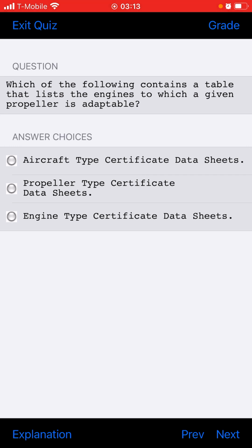An increased fuel flow indication on the gauge. In an aircraft equipped with a pressure drop type fuel flow indicating system, if one of the injector nozzles becomes restricted, this would cause a decrease in fuel flow with an increased fuel flow indication on the gauge.